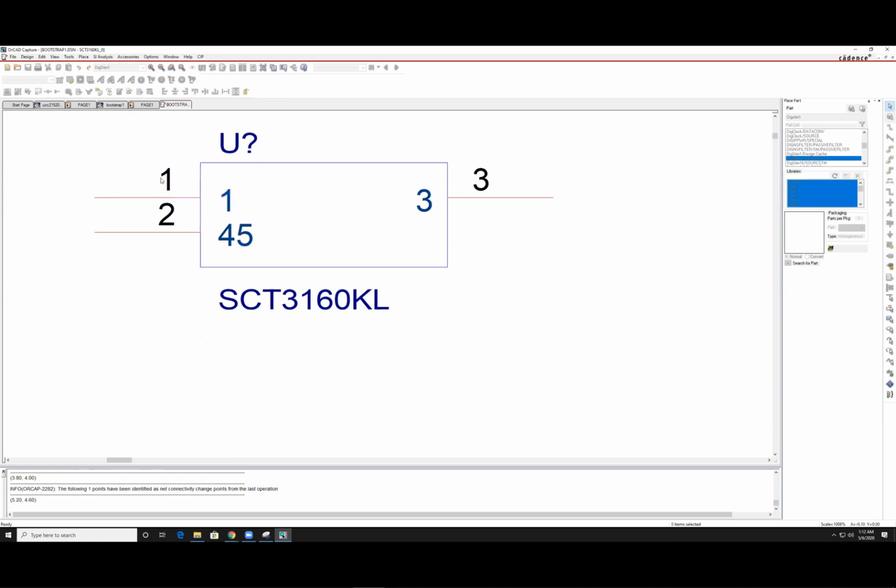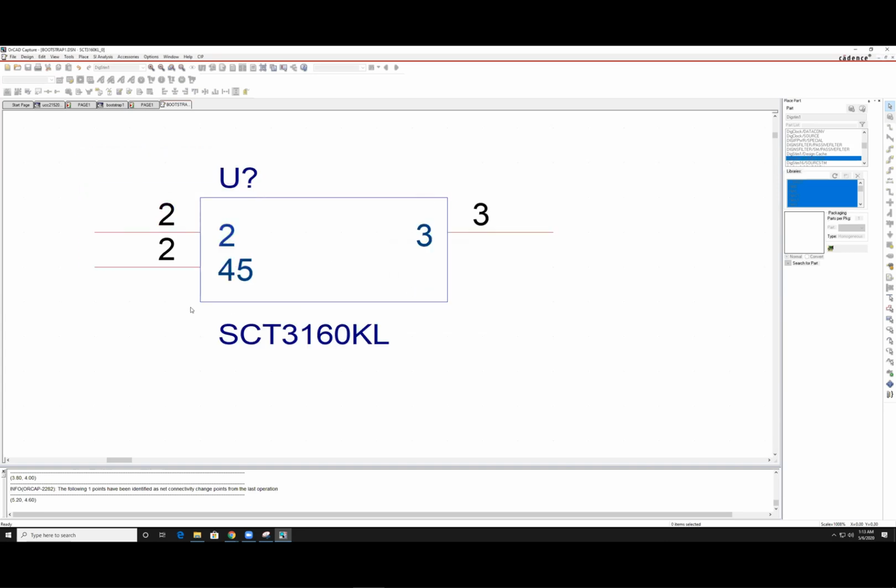So you want to click on the outside here. Notice if I double click here, there's no change. Even here, but if I click kind of on the outside, try to prompt the box, there we go, and double click. So you want to change this to value 2. Let's change this now to value, do this guy first actually. I think if you just click on the line, it'll let you edit it. And let's change this to pin 3.